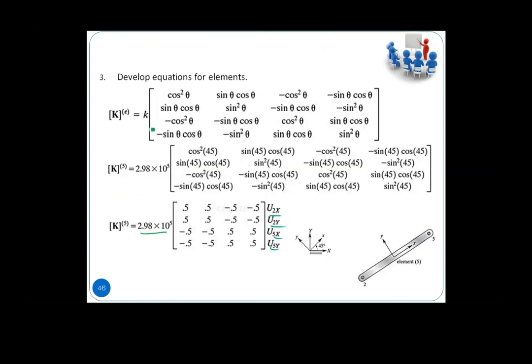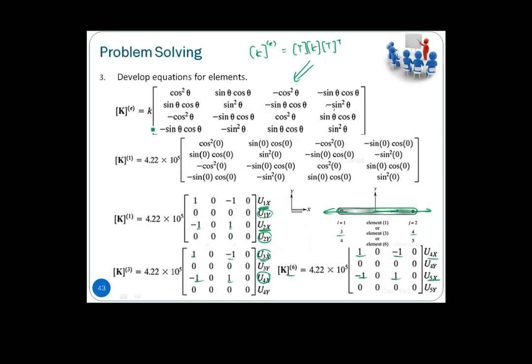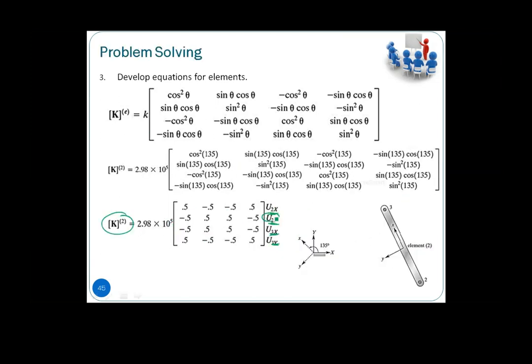So if you look into the second node, or second element that covers the second node itself. So beside this K1 itself, we also have K4, covering 2x, 2y, and 4y. We look into this 2y first, so it's 4.22. Then we also have this negative, we have also this negative 2.98 divided by 2 is 1.49 times 10 power of 5.